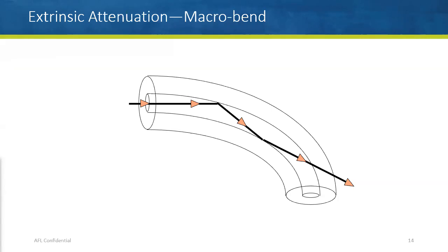Typically, your bend radiuses will be 10 times the diameter of the fiber. That's what we want to do. And that's not really scary. You can still make pretty tight bends with it because these cables are very small. A typical 12-strand fiber optic buffer cable is probably about 0.35 inches in diameter. So just take that into factor.